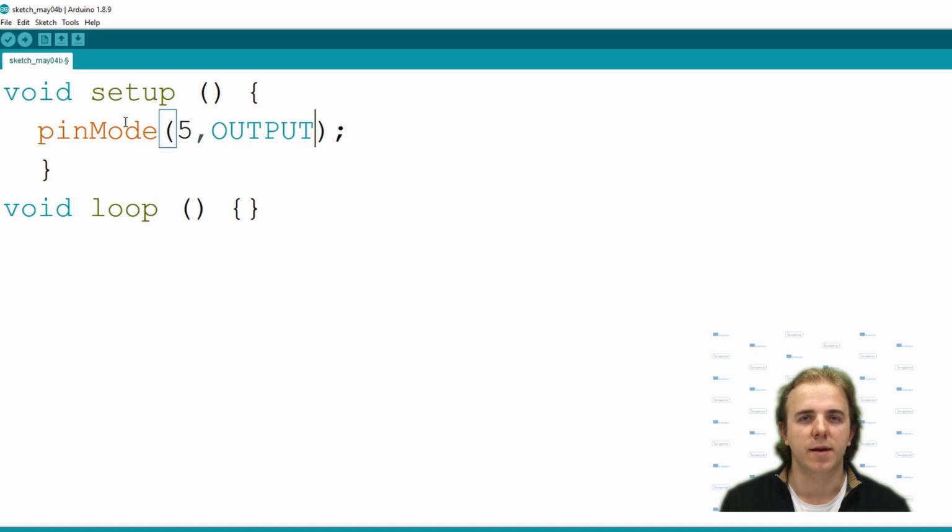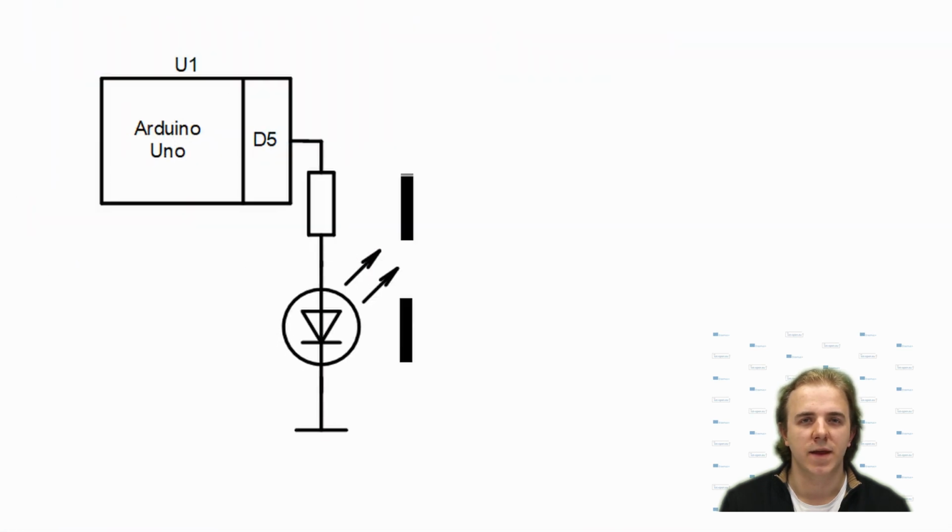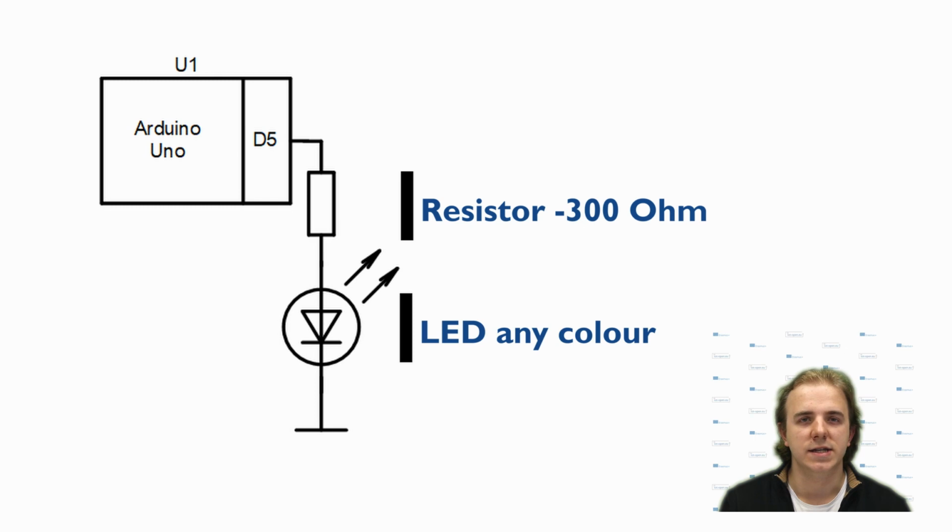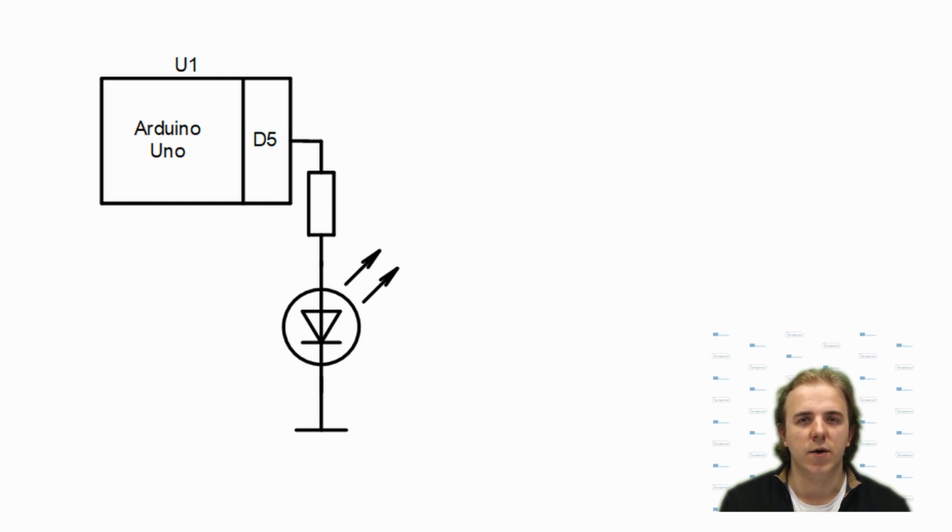If you define pin mode as an output, there are two functions that you can use with pin: digital write and analog write. Digital write will output either high or low level. It can be used to control digital logic, LEDs or other low power devices. As an example, we will make a simple schematic on a breadboard with LED and control it with our Arduino